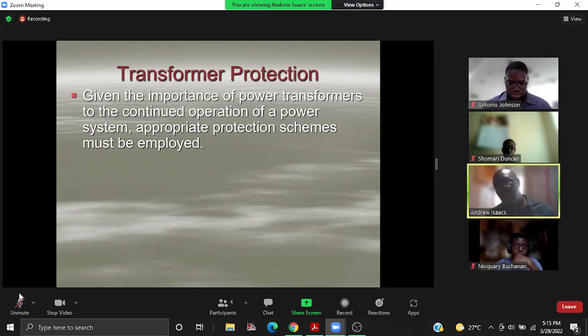So we have our delta, which causes zero sequence to stop at a particular point in the network, etc. So transformers are a very important piece of equipment, right? Yes, we appreciate the different voltage levels that it facilitates, but as I just mentioned, there are other uses. So it's important that we try and keep this particular part of the power system in operation, and we must seek to protect it